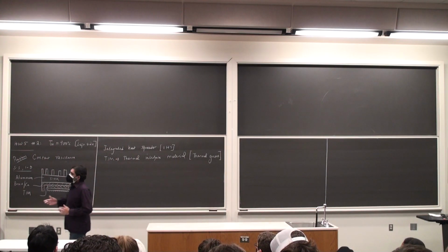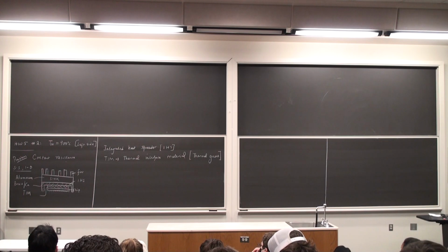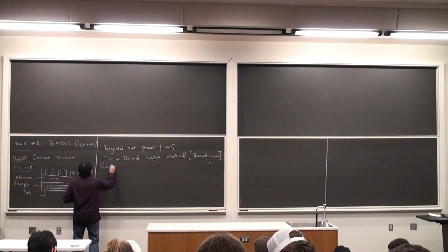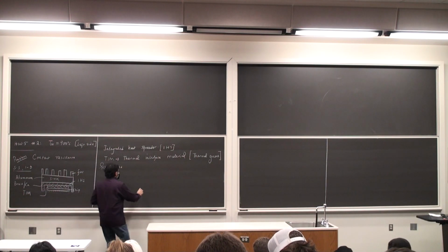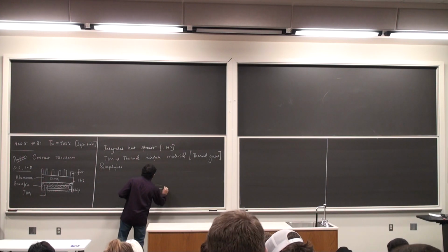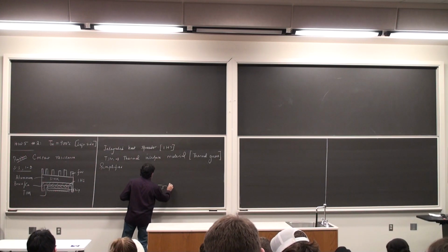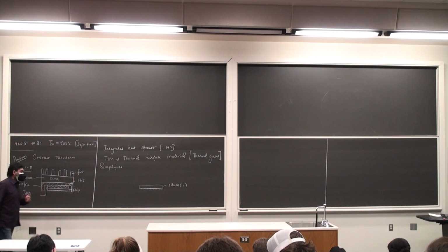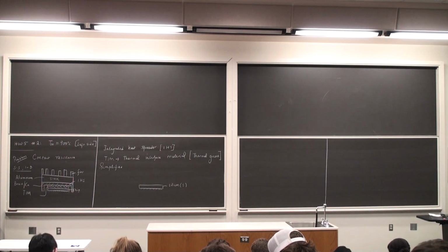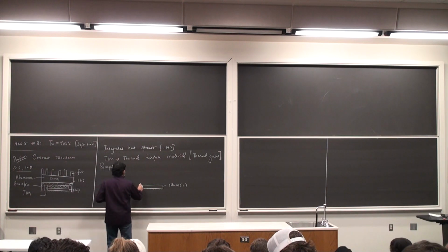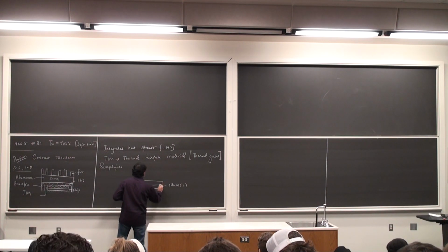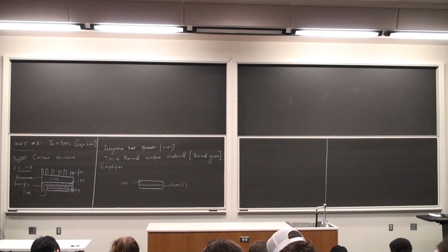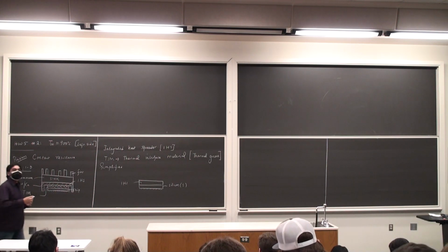So I'm going to simplify this situation, and I'm going to first look at the following situation. So, simplified case. Just a silicon chip. My symbol for that is S. Then let's say that for practical purposes I don't have this thermal interface material. Just bear with me. You will see why we need that. This is the IHS. You don't want it to be in direct contact with the chip, but let's say for practical purposes it is. And then on top of this is the heat sink.